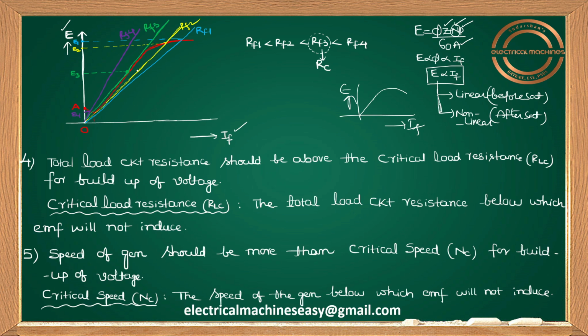So this one I just explained here. Please try to see your red color waveform, the red color graph, guys. But the thing is, if you observe clearly, whenever field current IF equals 0, here I just showed E equal to 0. To be frank, E is not equal to 0.